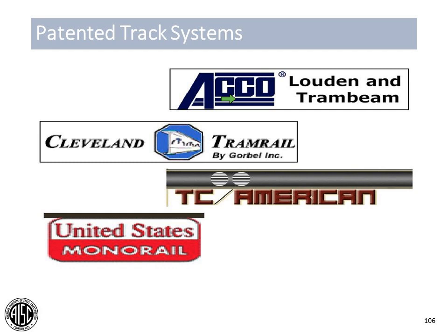But if you're designing something without a crane manufacturer known, there are ways within the AIST tech report that you can calculate recommended end stop forces based on your crane capacity. Or you could look at what's something that works for me and basically offload that onto the crane supplier as well. So there's a couple of different ways, and it depends on how you're going to get the information to complete your design.